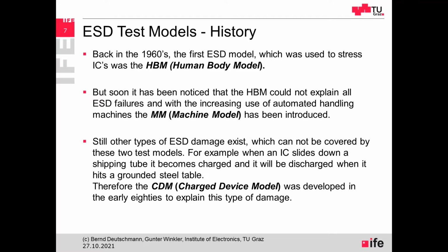So they were produced, they were handled, they were shipped to the market, and then at the end, the final product was not working properly. And then they made a lot of investigations, and finally they figured out that these integrated circuits were somehow damaged. They had a kind of pre-damage while they were shipped to the customer. And then after quite a lot of investigations, they figured out that this pre-damage might be caused by electrostatic discharges. Electrostatic discharges from human persons who were handling these integrated circuits.